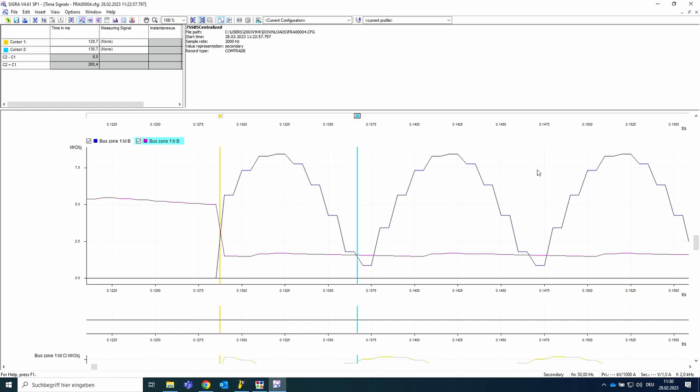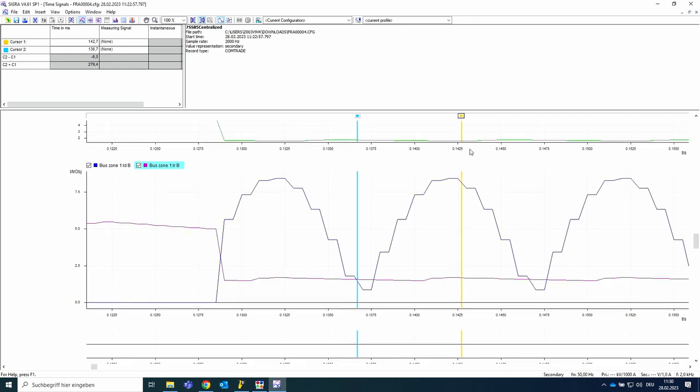Here we will start once again a measurement window of 6 milliseconds. So for at least about 1 millisecond, we will have no threshold exceeding. But immediately after, we will have the threshold exceedings, and at the yellow point, that's the tripping. That's 6 milliseconds later.